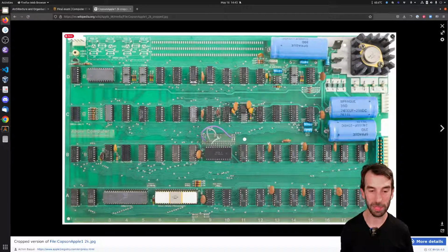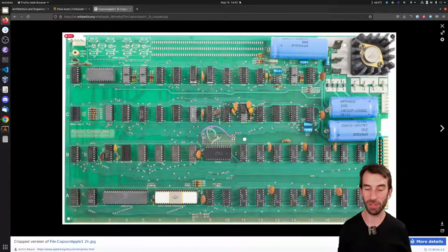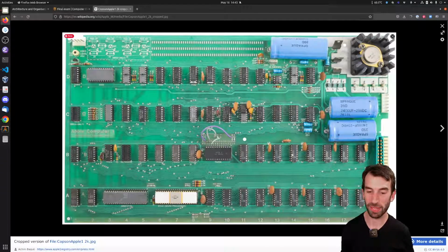chips. All these chips that start with a 7-4 probably contain 4 logic gates. That's the typical arrangement. They'll have 3 legs, that's a logic gate, that's a logic gate, that's a logic gate, that's a logic gate. So that lets you set up a little system for addressing the memory. So I think each one of these is half a K of memory, 512 bytes.